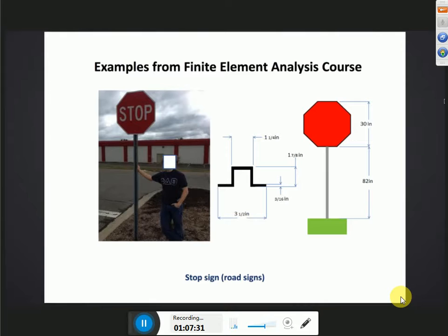Just one outside their campus, or if they're going to a city, and if there's nothing, then they can explore from the internet, from other resources. It's a very hacked section, and discuss why it has to be hacked like this. Why not I-beam? Why not rectangle? Why not box section? Why not round? And then there are holes in it. Why should there be holes in it? To escape the wind. So this will bend, also twist. Torsion of this is very tough.